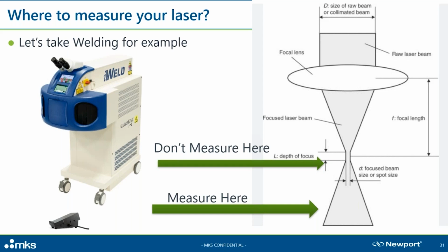We started out with Zap-It paper to estimate the beam size. We ended up switching them to a pyroelectric sensor because the welder was emitting pulses, not a continuous beam, and had them measure well below focus. This stopped the damage from happening, and they even bought a camera to measure their beam size. That's when it really clicked for them. Seeing the beam size change in real time was the real light bulb aha moment.